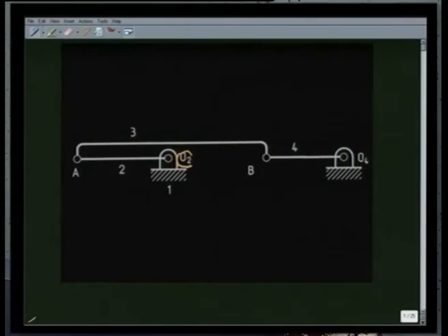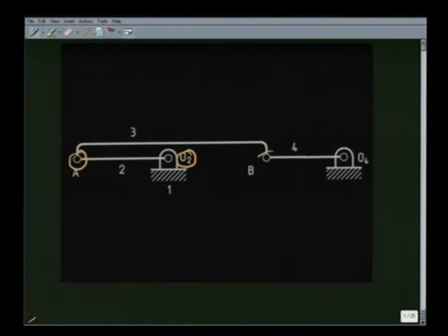Let me now summarize what we have just seen for a transition linkage with opposite sides of equal link lengths. Here, as we see, the 4 revolute pairs, namely O2, A, B and O4 have all become collinear. As a result, all the links become collinear, and from this configuration onwards, the linkage moves in a non-unique fashion. If O2A is driven in this direction, O4B can move in this direction or can flip back in the opposite direction. If it moves in the same direction, then it maintains the parallelogram, whereas if it moves in the opposite direction, then it flips into the anti-parallelogram configuration.